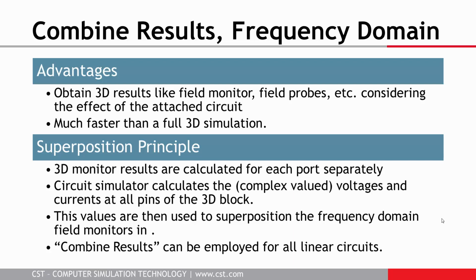And we start first with an example in the frequency domain. What combined results is doing, it allows you to visualize the fields and currents with the attached circuit, but as a post-processing step. We are not putting all the circuit elements into the 3D model. We are calculating a set of voltages and currents at each of the pins of the circuit and at each of the pins of the 3D block. And each pin of the 3D block corresponds to one port.